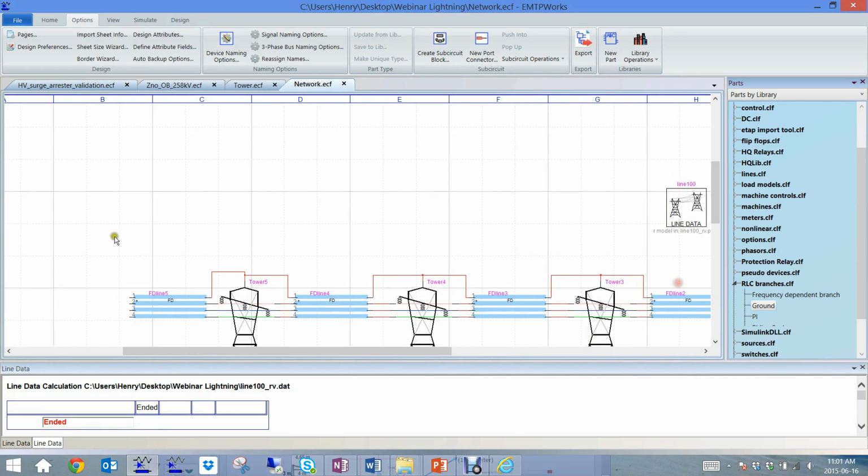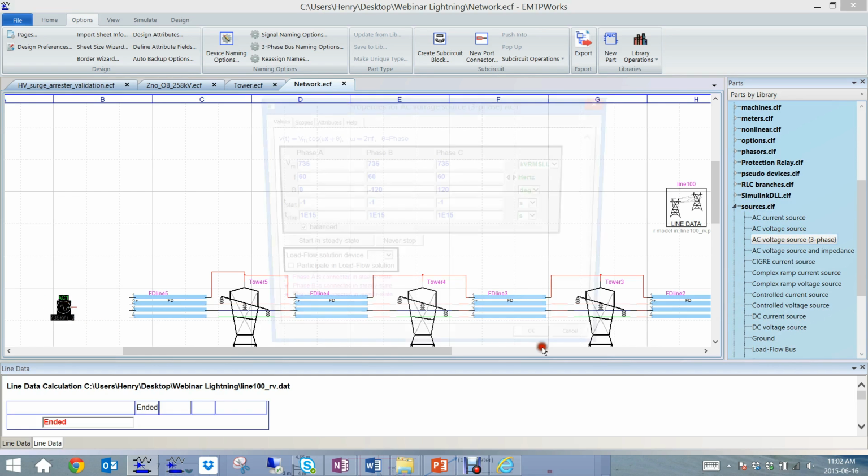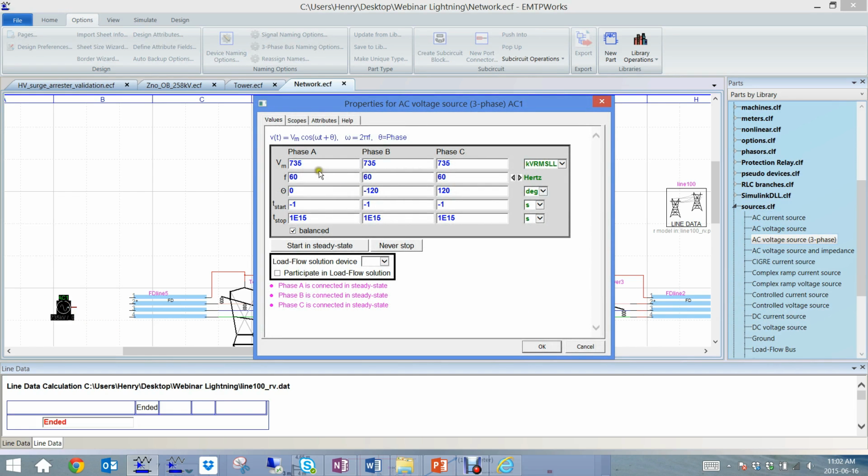Okay, so then here I put a Thevenin equivalent or even just a voltage source of the rest of the network. The voltage source is 64 kV. Actually, we work at the frequency of 50 Hz. The data we have are from Europe, and this is it.